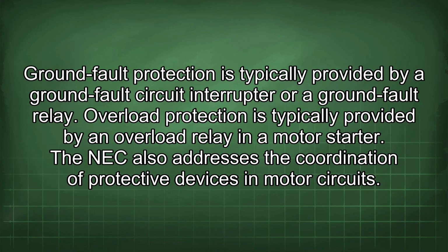Ground fault protection is typically provided by a ground fault circuit interrupter or ground fault relay. Overload protection is typically provided by an overload relay in a motor starter. The NEC also addresses the coordination of protective devices in motor circuits.